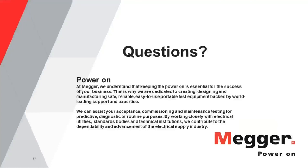And another thing in consideration is whether equipment has been operating or not. So if you came in the morning and the facility has been de-energized all night and you tested a motor, for instance, you'll get a pretty high reading most likely. If the motor had been running half of the shift and then you shut it down and immediately do a test, obviously it's going to be warm, and so the reading is going to be decidedly lower.